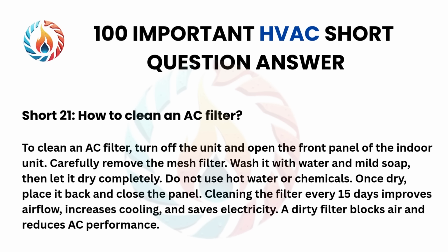Once dry, place it back and close the panel. Cleaning the filter every 15 days improves airflow, increases cooling, and saves electricity. A dirty filter blocks air and reduces AC performance.